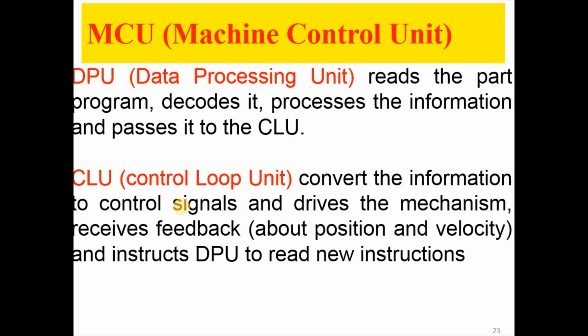So I want to create block number 1, that is N10 G00, a rapid traverse to X0 Y0. Okay, this is the first line, only the rapid traverse of the tool. Second, N20 G01 linear interpolation X20 Y20. I want to traverse this tool from 0,0 to 20,20.